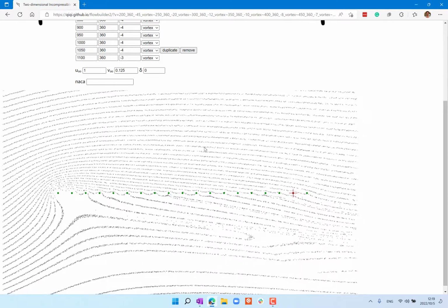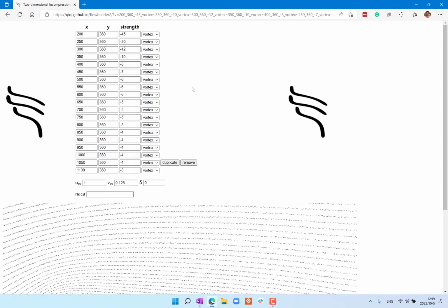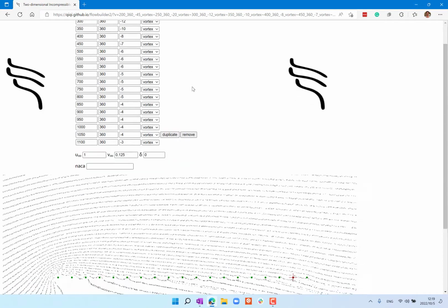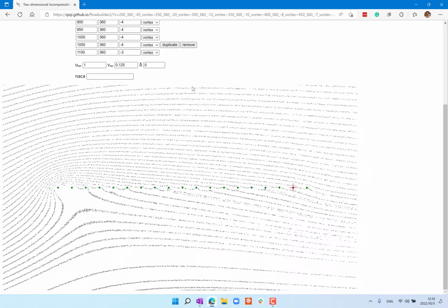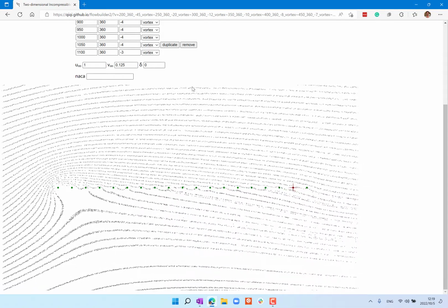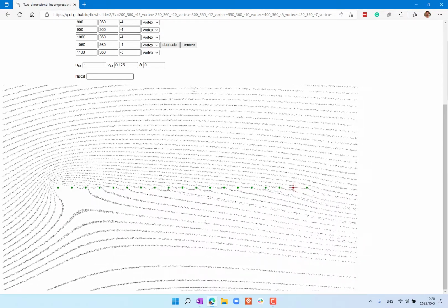The y directional velocity over here is just the sum of all the individual components. If it's originally equal to 0 and I halve all the components, it's still going to be equal to 0. So basically what I need to do is go through all the strengths and make them half to make the flow still parallel. I'm not going to do it, but you can see that's going to be true. And if I double the y velocity, I can just double the strengths to keep the flow at 0 in the y direction across the flat plate.